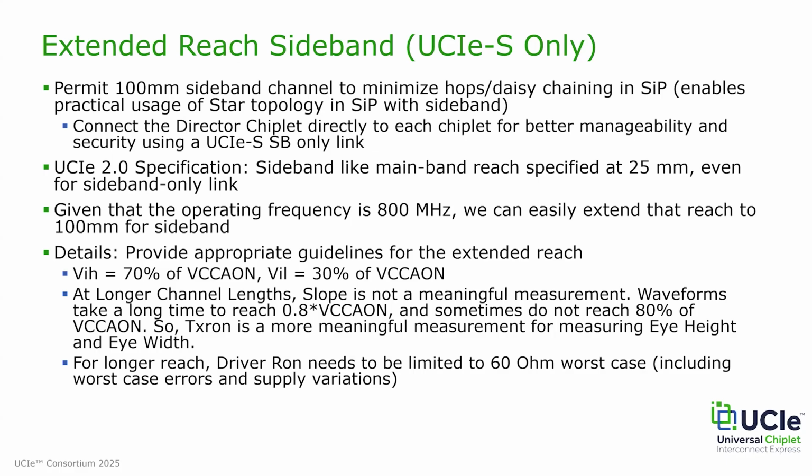It has the benefit of getting higher bandwidth, lower latency, and of course, better security characteristics because you are not going through other chiplets. So, especially with complex systems, this is very valuable. And the question then is that 25 millimeter is a restriction, especially with large packages. So we extended that reach to 100 millimeter.